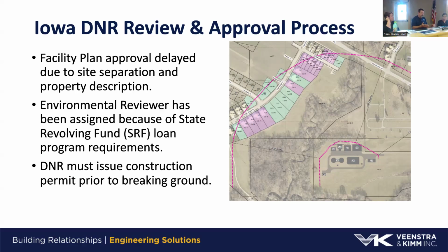We've got the grit removal, we've got screening, we've got things that are going to require daily attention. There's a sampler out there. All of that stuff is going to be close to that admin building by having it up front. If we push it to the back, now you're increasing your travel distance for every trip you have to make there. So that was discussed quite a bit, and they would prefer to have that admin building at the front of that plant in that location for those reasons.